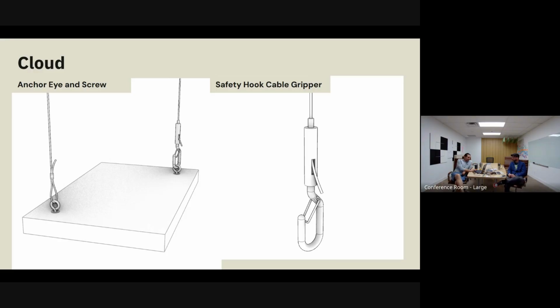Talking about spear clips, can they be placed for wall and ceiling applications? Yes. For the spear clips, as well as the construction adhesive and pin nails, both of those are wall or ceiling applications. What's the difference between peel and stick and construction adhesive?